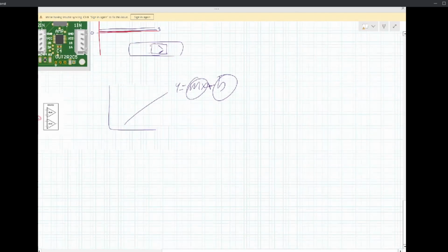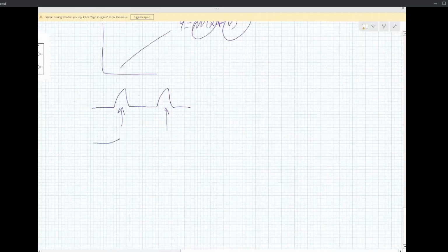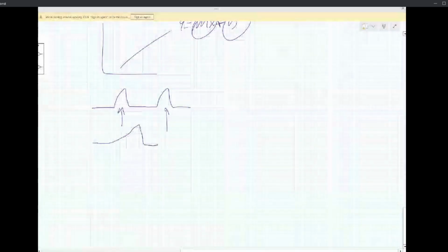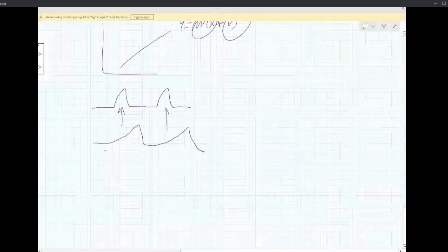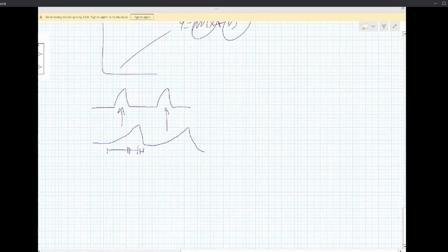The oscilloscope is going to look like you're going to have nothing, nothing, nothing, all of something, something, something, and then nothing, nothing, nothing, also something. And these are when you're applying your loads. It should look more like this, go and then go. This is when you're actually applying the torque, and this is when your torque wrench clicks, and then all of a sudden you let it go because you get scared. And then this peak voltage is what you put into your Excel. And that is how you calibrate.